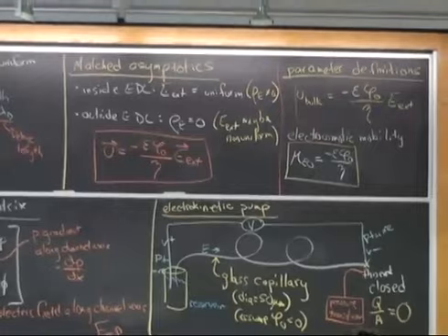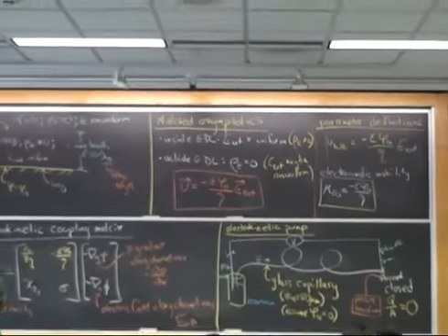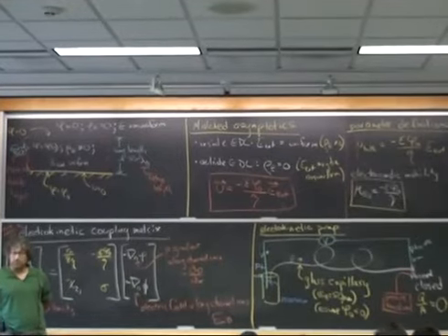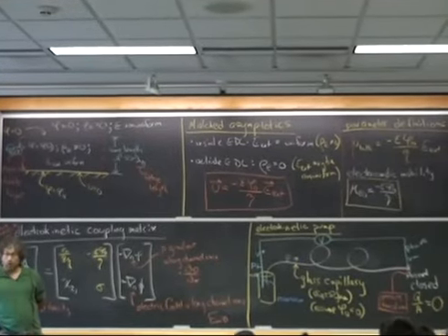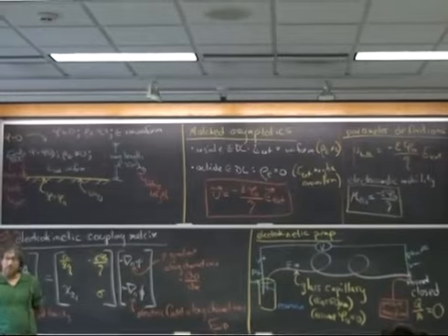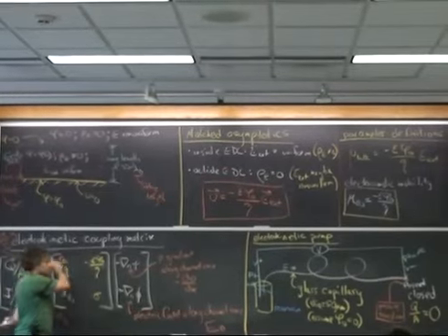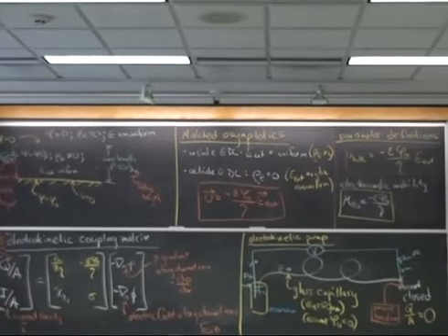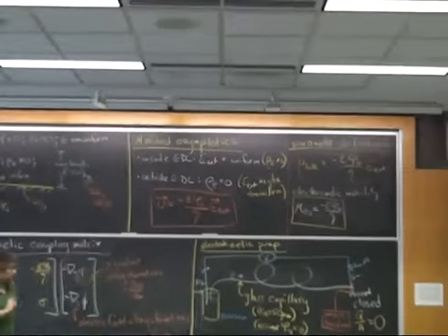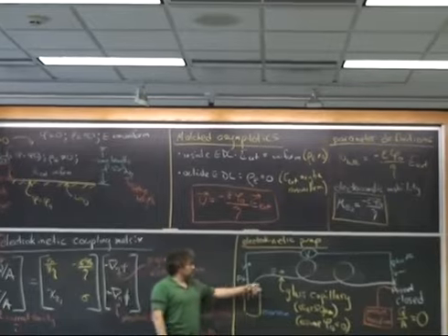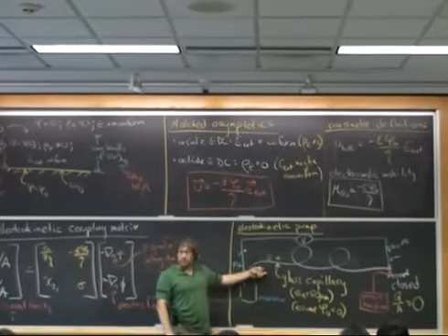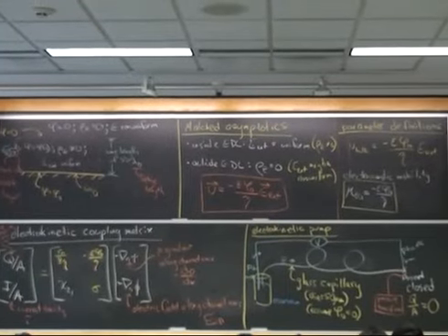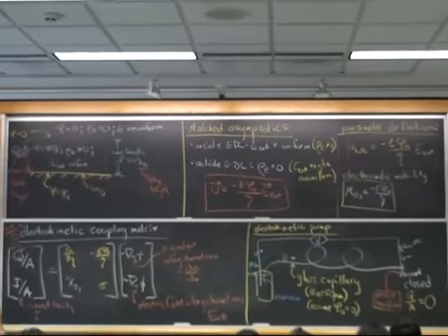Yeah, so the key thing, if we want to measure the finite time for the system to come to equilibrium, we have to factor in the compliance. If we don't have any compliance and the system is rigid, the system will almost instantaneously come to steady state. Within the approximations we're using of these equations, it will come to steady state instantaneously. In fact, there is a finite time for things to start up, etc. And if this system has a bunch of compliance, then there's going to be a finite time required to bring this to equilibrium, which is going to be proportional to both the hydraulic resistance and the hydraulic compliance.